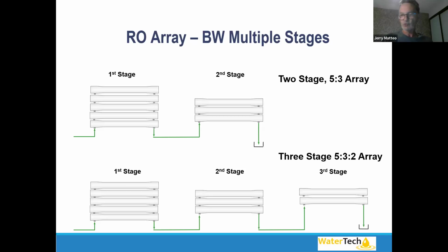But this way they know what they're working with, and they can add a known amount. I think they use potassium, I think magnesium, a few minerals they add back in. So they're taking permeate or product water through another whole separate RO. I didn't show it here with an illustration, but that's what it is. So stages is concentrate, pass is permeate.